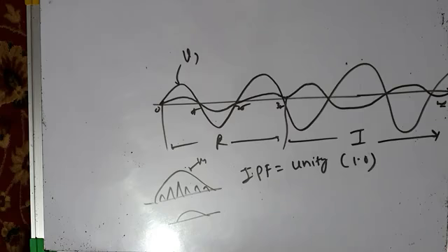Okay, then I also told you that when you use hysteresis current control technique, when you use boost converter, the boost converter should always be used in closed loop control. It should not be used in open loop, because in open loop there is a danger of the load getting dangerously high voltage.